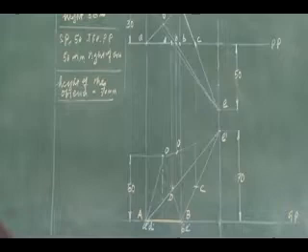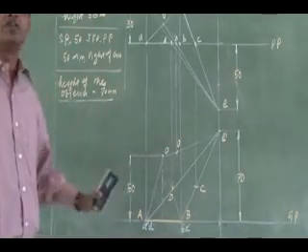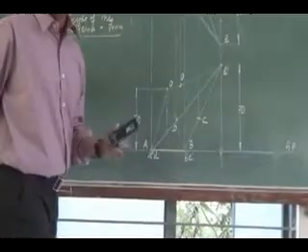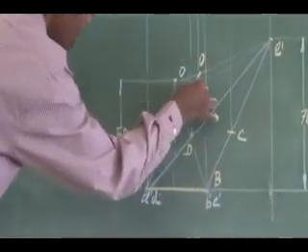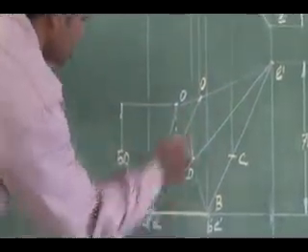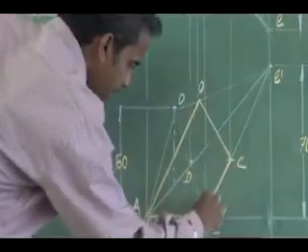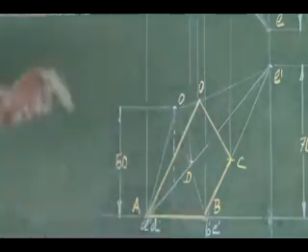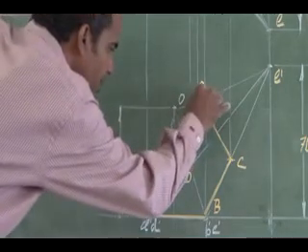See here. Now you have to connect these corners. First of all, the visible edges we try to show. From apex to all the base corners, I have to show the slant edges. So from O to A, I can join and show a slant edge. B to C is a base edge. Similarly, O to B, I have to show a slant edge, visible in my perspective.